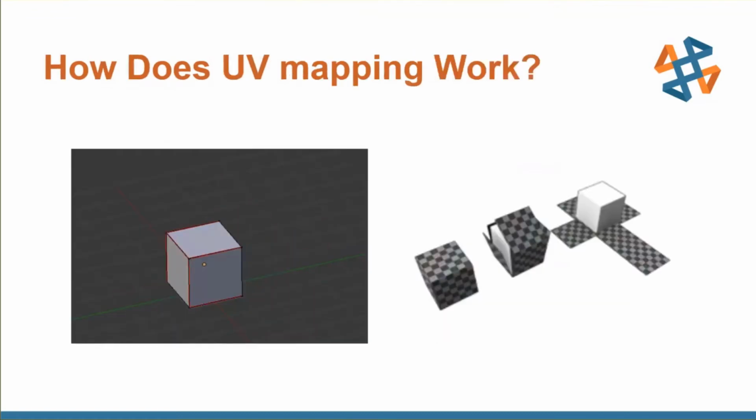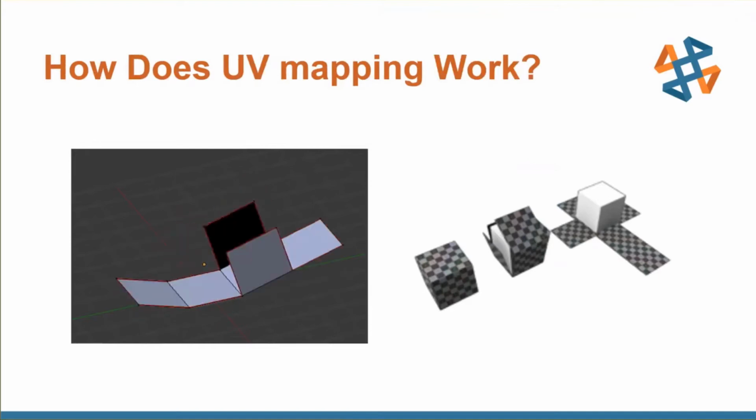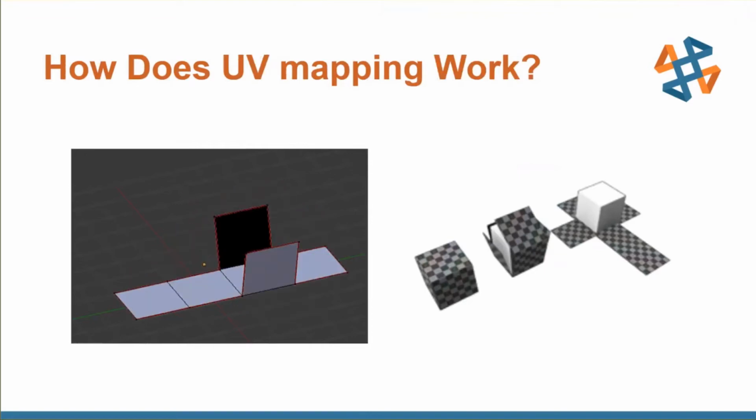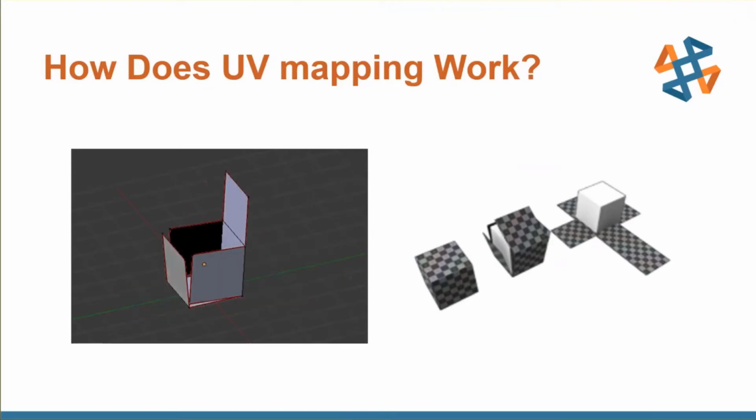And why these direct modeling softwares are using quads is because of this workflow called UV mapping. UV mapping is basically this concept of unwrapping your model, laying it flat, and then projecting an image to that flat plane. And it's called UV mapping because UV denotes a coordinate system in 2D space for a 3D model that's laid flat, and X, Y, and Z is already in use, so they started using the letters U and V.